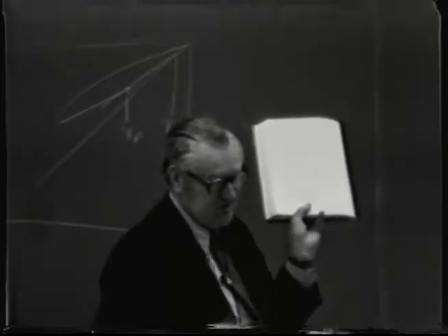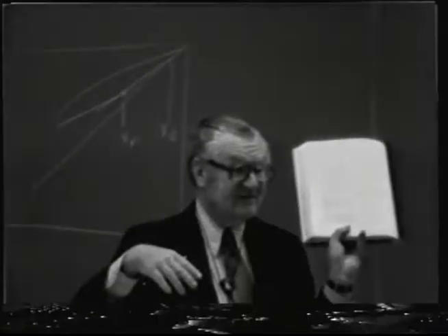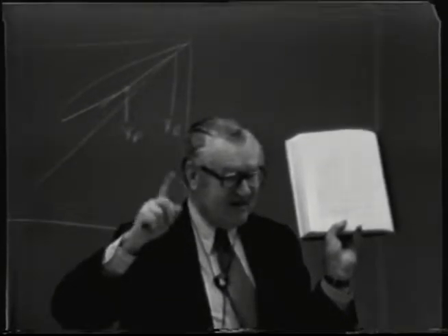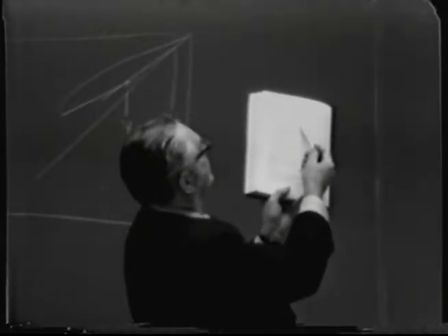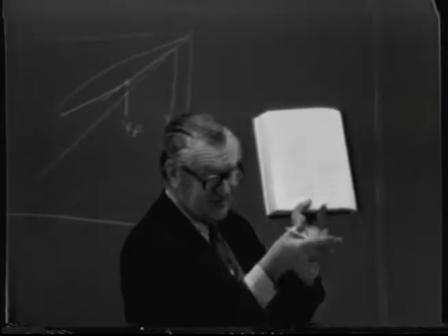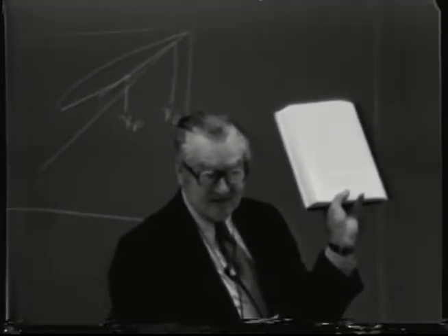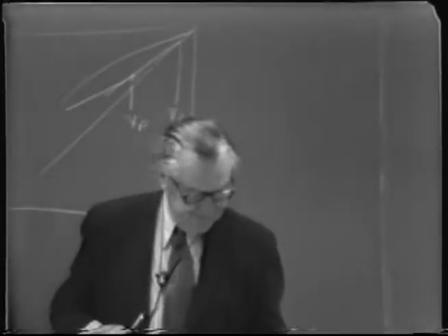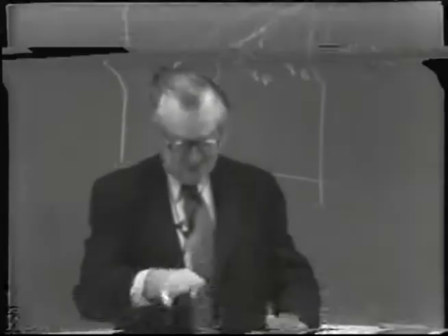Because down in this very low region, we're essentially dealing with Henry's law, that y is equal to kx. In other words, the k constant is about 10.8 to 1 in this very low region of alcohol concentration. Then the operating line, plotted on a log scale, becomes slightly curved. But it enables the steps to remain essentially the same size when you're stepping off stages, so you can read them all quite accurately. I've done that for this particular case, but I didn't bring in the solution with me.